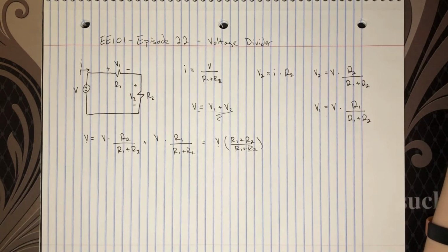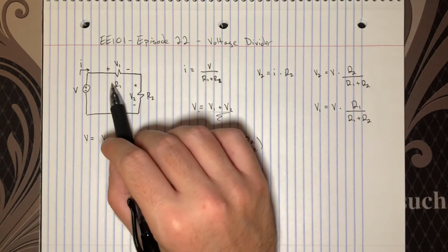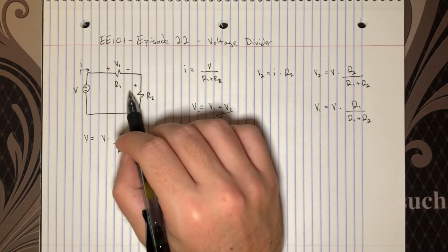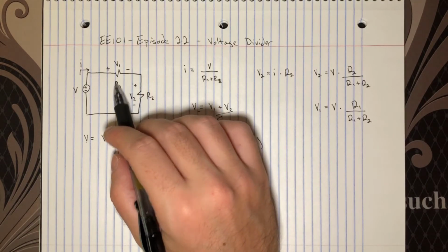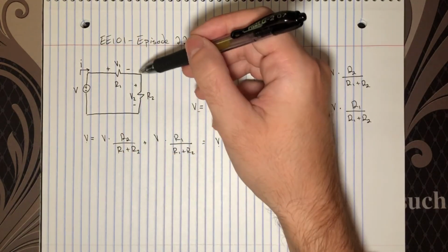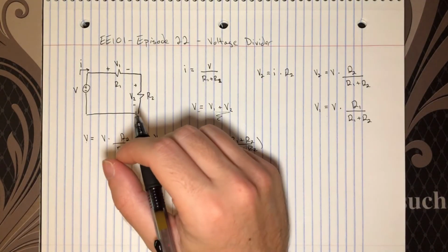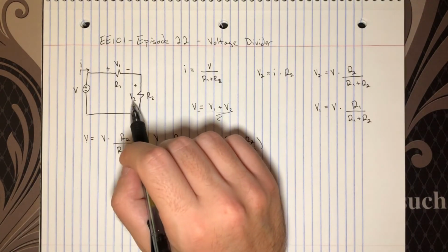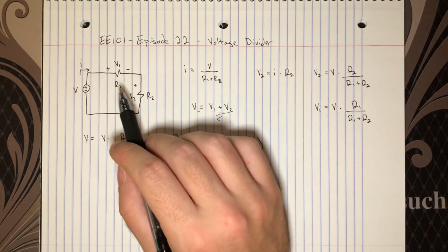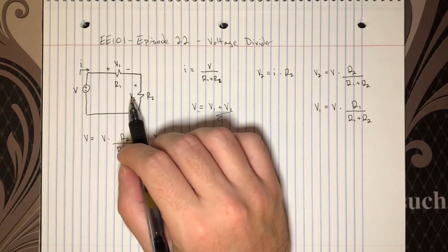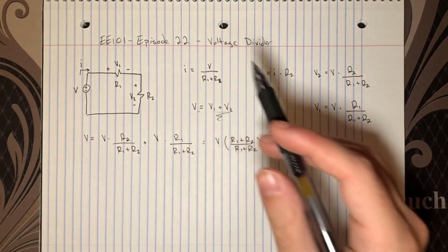It's such a fundamental concept because, in fact, literally any two series resistors form a voltage division. And really all it takes is two impedances that share a node. And so you'll see this absolutely everywhere. And these don't have to be resistors either. There are more complicated circuit elements that we'll put in this situation and analyze. But it's just fine to talk about resistors for now.